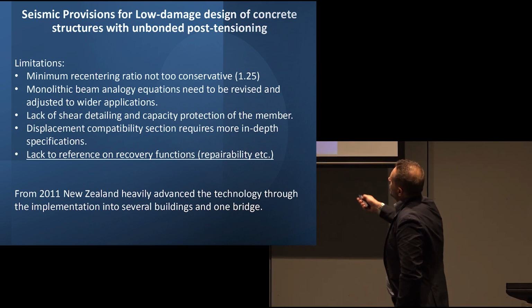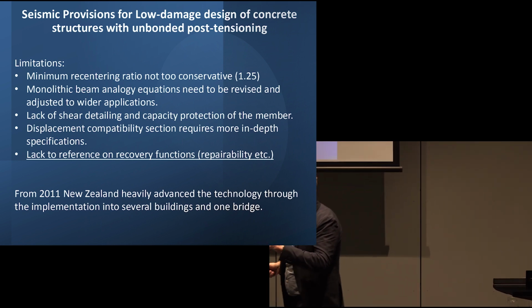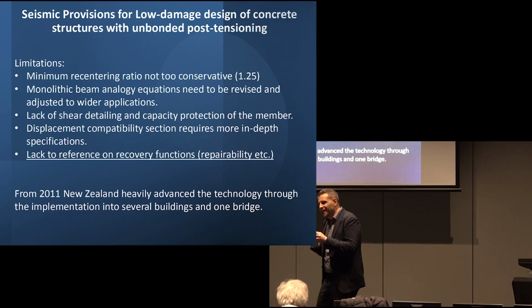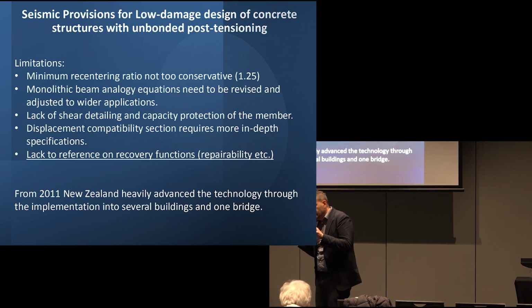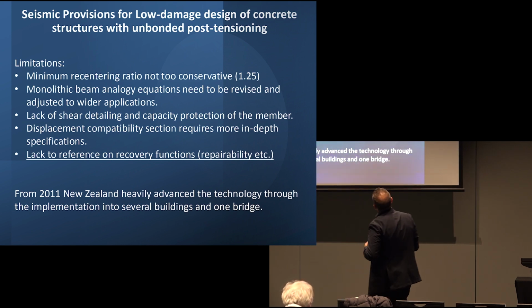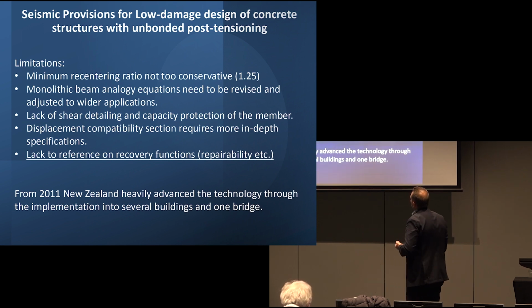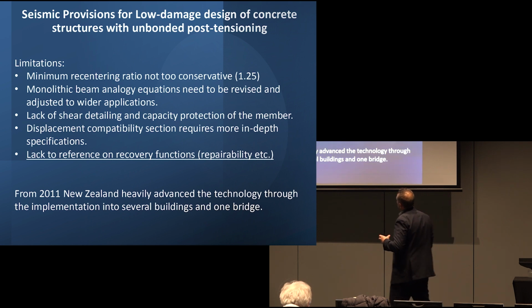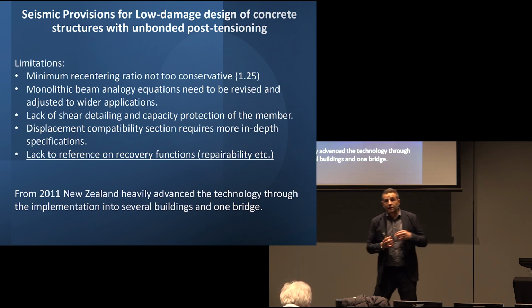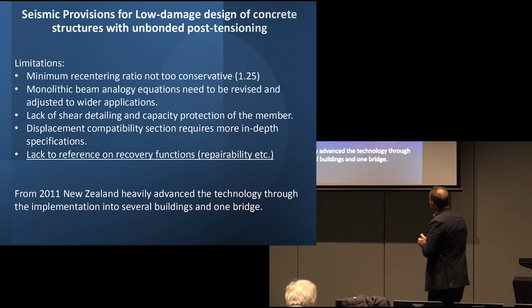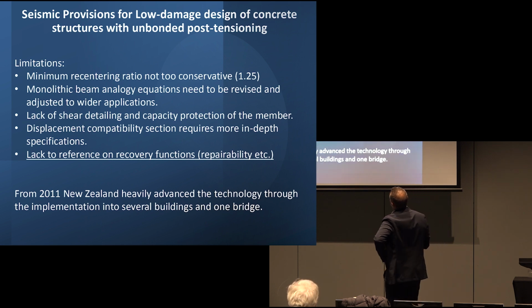So there are a few parts in that section, which I think is very high level, that are missing: the recentering ratio, the monolithic beam analogy that has to be adapted, the detailing, and the capacity protection of the members. We made further improvements. And to me, because we talk about resilience, we need to start connecting this to the recovery function, repairability.